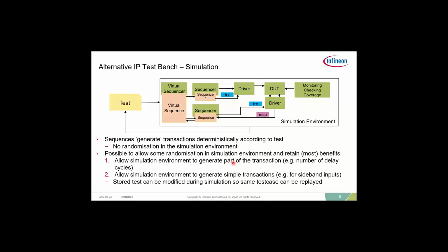Is that correct? Yeah. Your environment will interpret your test to generate these transactions. A very simple example is if you want to configure a particular register to have a particular value, you can just put the register name and value in your test, and then you will generate a transaction which writes that value into the register inside the design.